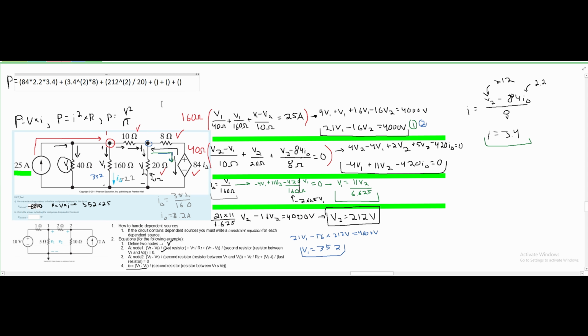So we have our resistance right here. We don't know the voltage flowing through it. The easiest thing to do here would be to find the current flowing through it. And we can use the same formula that we've done twice over now. We can say that our I, and we'll call this of the 10 ohm resistor, and I'll actually just label this other one as the 8 ohm resistor, just to keep things nice, is equal to our V1 minus V2.